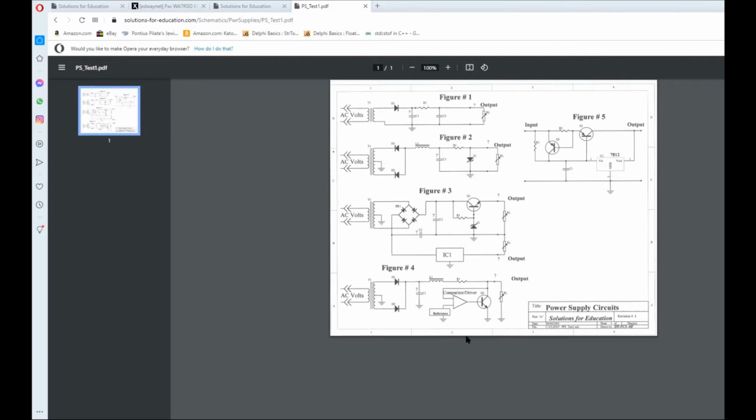Now let's come down here to this one instead. This guy down here has an amplifier here, which compares a reference voltage, whatever this might be, with this voltage here. So this circuit right here is simply a linear comparator. By the way, this is usually at least half a dozen transistors. You can make one out of any number of different components. But the whole point is that whatever this voltage is compared with this guy here tells this transistor to conduct more or less. Now, this is a shunt regulator.